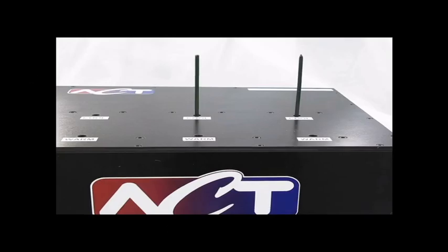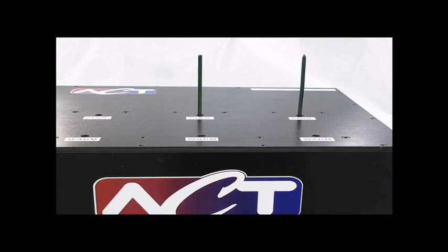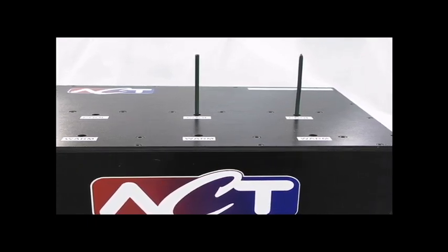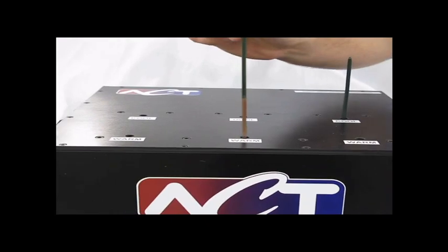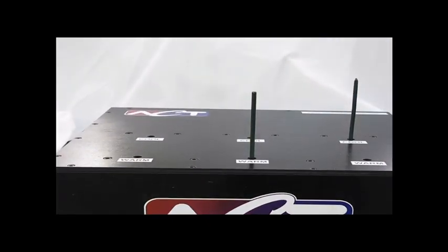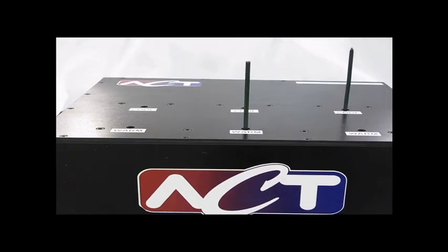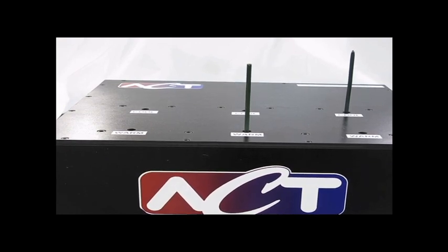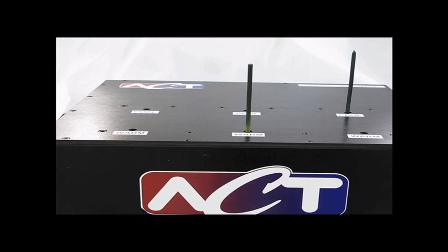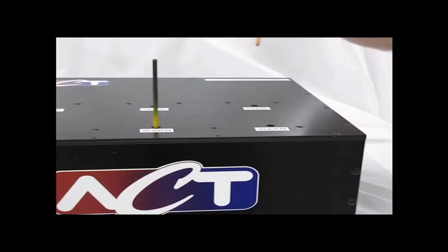In this demo, we'll examine the heat transfer capability of a copper rod versus a heat pipe. On the outside of both samples, there's a paint that changes from green to yellow when the temperature exceeds 40 degrees C. We'll now place the copper rod into the hot side of the unit and let it heat up. The hot side is well above the 40 degrees C color change temperature. Copper has a thermal conductivity of 400 watts per meter K, which is high for most metals. You can begin to see color changing as the copper conducts heat away from the heaters below.